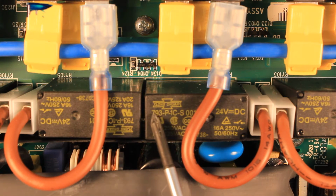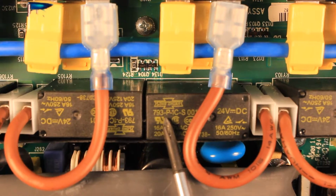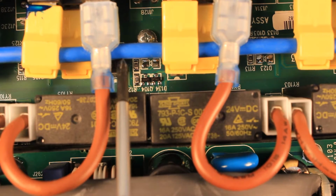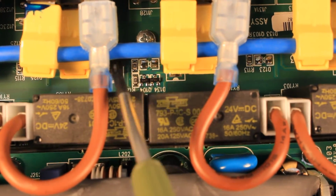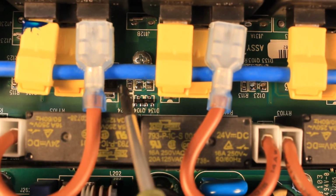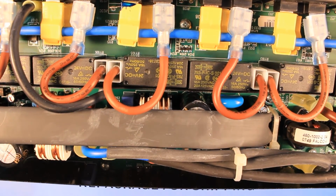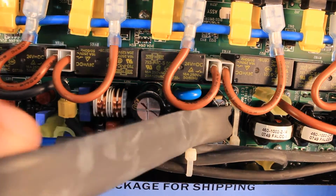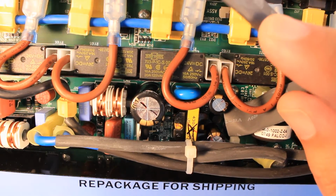Since when the relay is being de-energized, there is a huge pulse being generated, and in order to take care that this pulse is not destroying the electronics, notice these larger black diodes on the PCB. It's really hard to show because I don't have much space due to all the cables. Then regarding the two switching mode power supplies, or the other board in general, I actually removed this cable out of the way so we can see what is going on here.